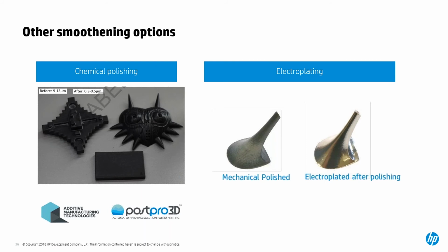So when we are dyeing the parts, what we are doing is saturating the material, but for a short period of time. So the parts are swelling, and we have quantified that. The increase in the dimensions is around 50 to 100 microns, but again, it will depend on the surface quality, on the size and the geometry of the part. So one of the options is to scale down the parts to absorb the swelling that is going to happen afterwards.